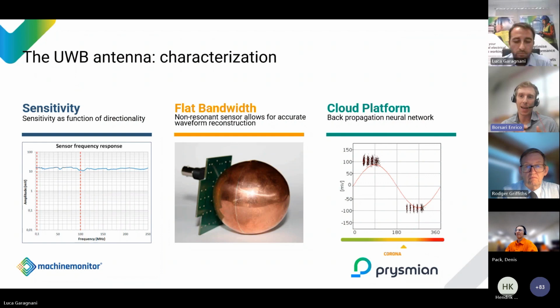By placing the device next to the source of the discharge, we get higher amplitude from that location, and we are able to use the noise immunity capability of the device, because what comes from elsewhere will be naturally reduced in amplitude.